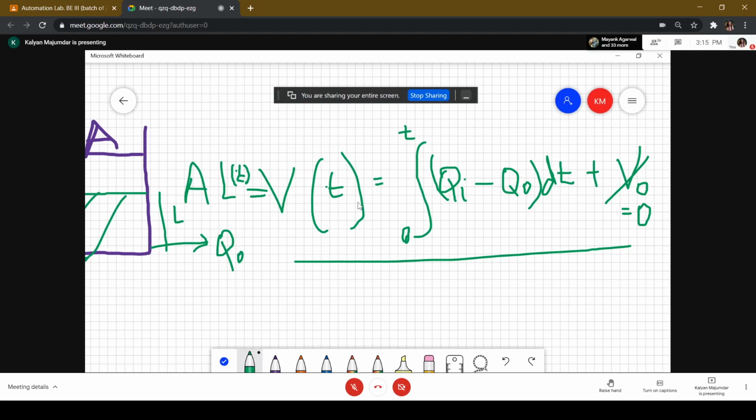So here, as we said at the very beginning, to keep the experiment time reasonable, let's say the fill-up time should not go above 10 seconds. If we sit around for half an hour, that makes no sense to process your logic. So that would depend upon the cross-sectional area of the tank or the flow rate. So you can either choose an appropriate flow rate, or you can choose an appropriate cross-sectional area to ensure that your tank fills up within say 10 seconds, so that you can do your experiments or the whole thing pretty